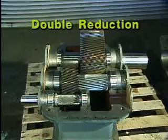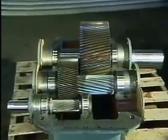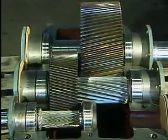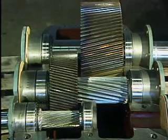This gearbox is a double reduction type. It steps down the motor speed in two stages. The first stage of speed reduction occurs across this helical pinion and gear. The second stage of reduction occurs across this pinion and gear.